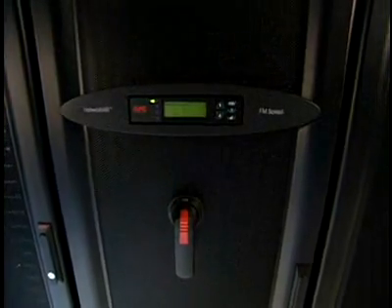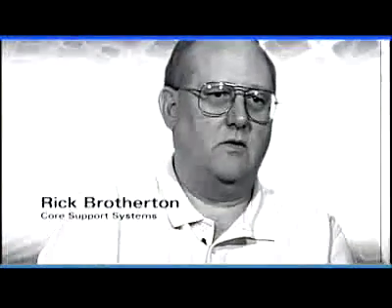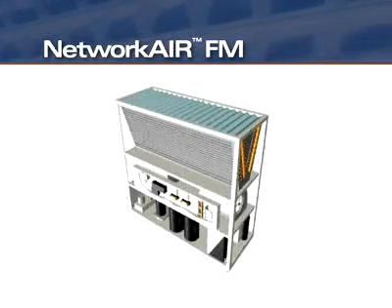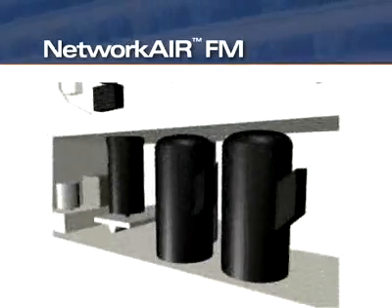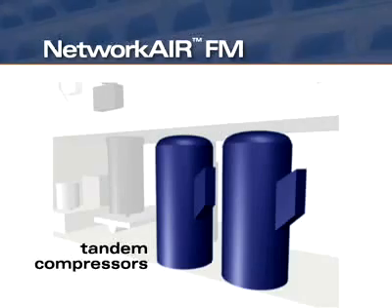The Network Air FM also offers front access for ease of service. Now we have the smallest footprint in the industry. It's all front access, so you can put equipment right up to the side of our systems and make use of the space that was once reserved in the past for service space, which is now usable space to the IT department. The Network Air FM utilizes tandem scroll compressors for capacity control, matching the cooling capacity to the heat load in the room for optimal efficiency.